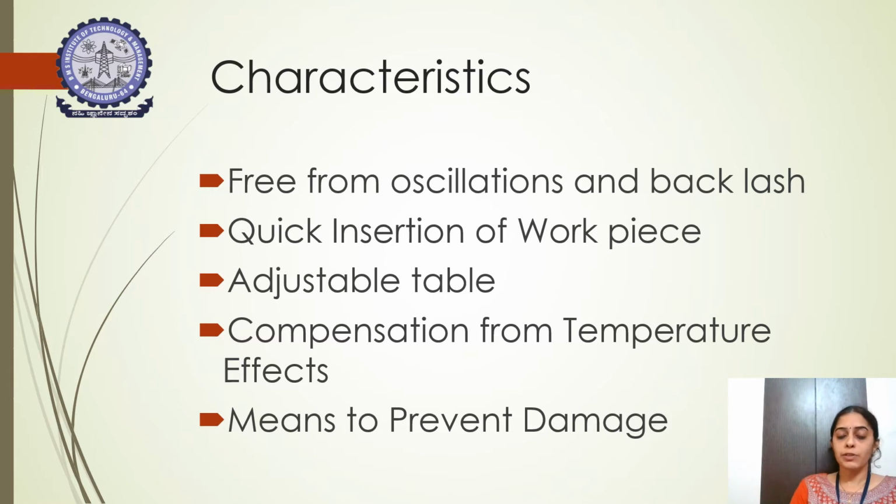Compensation from temperature effects. It is not affected by the temperature, or the temperature effects could be overcome, and also it helps to prevent damage. The damage to the workpiece or to the standard is very less while using the comparator, as there will be a smooth flow of movement between the workpiece or the standard with the plunger.